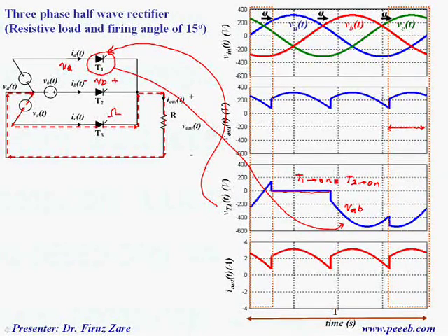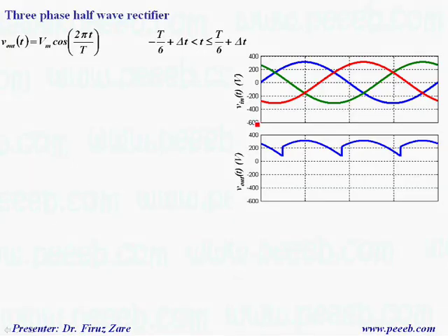And here, because the voltage across this thyristor is VA minus VC, over this cycle the voltage across the thyristor is VAC. So that means when the thyristor is off, line voltage appears across the thyristor. So in order to find the output voltage in a simple way, we need to move the time frame. That means we just move the axis from this point to this new point.